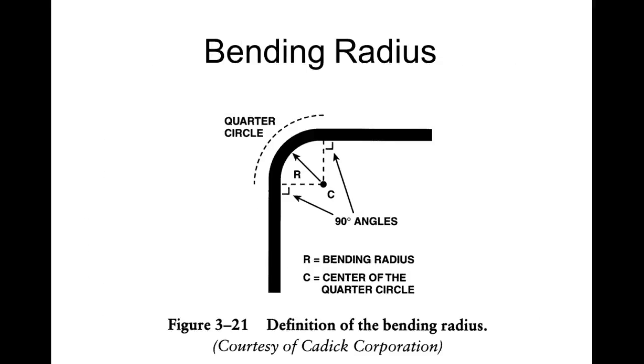And of course, we'll look at the bending radius. You have to maintain a radius of the bend. We don't want it to be too sharp. Why don't we want it to be too sharp? Yeah, it increases the pull tension when you're coming around it. And we don't want it to be too long or it eats up a lot of space on our wall. So we don't want it to go like that, right? So there's definitions. So the bend radius, and what's nice about most of your conduit benders is they are actually designed to give you the right bend radius.